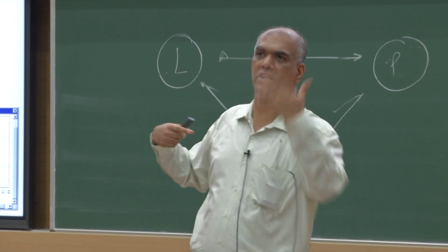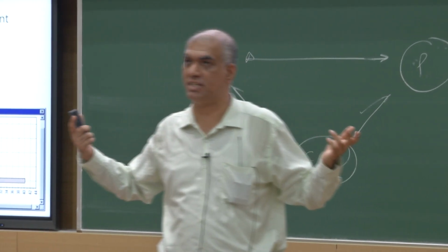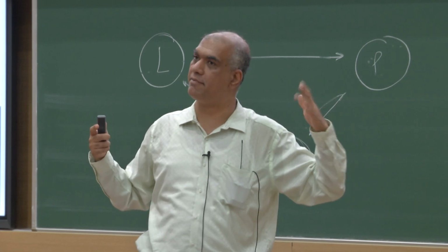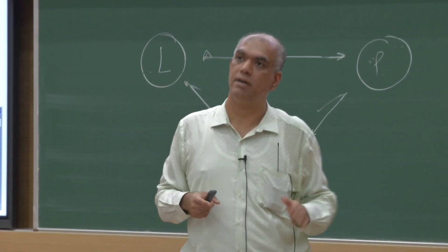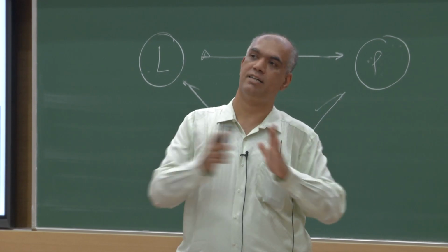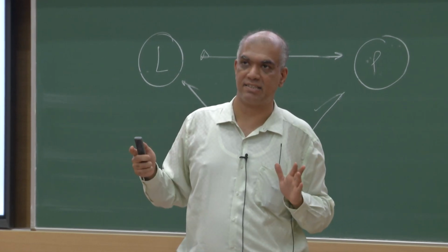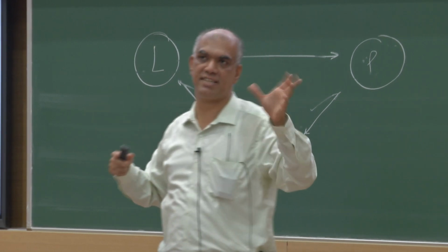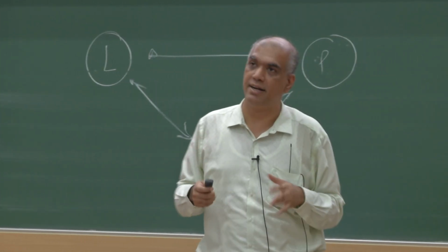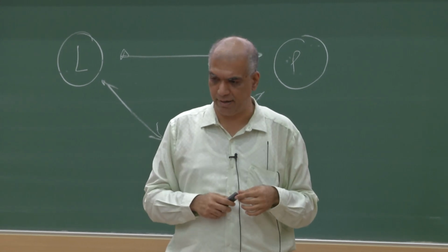I've gotten a question: what do I do for a batch process? Do I do a PFD? Sure, you do a PFD, P&ID, but how do you convey a batch process? This is one way to do it. Equipment on the y-axis, and the operations on the x-axis, right? So this is how you convey how a batch multipurpose or even a single product batch plant is going to use different equipment.